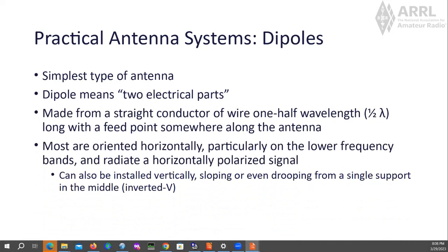Most are oriented horizontally, particularly on the lower frequency bands, and radiate a horizontal signal. Can also be installed vertically, sloping, or even drooping from a single support in the middle, and that's called an inverted V.